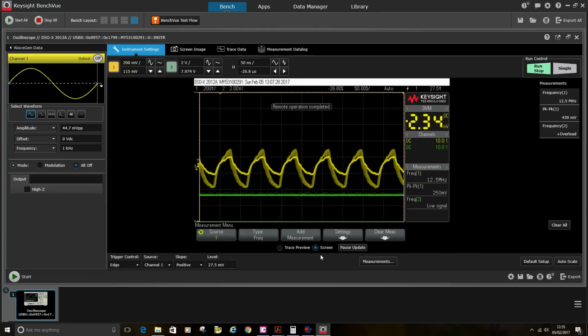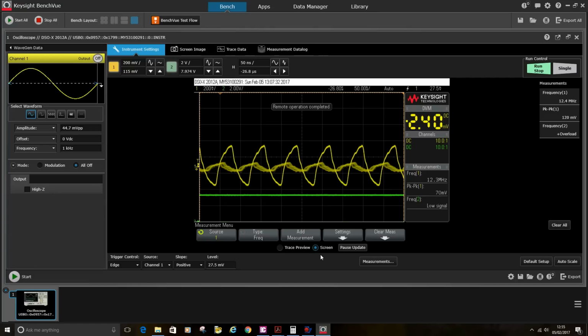Asked the supplier if they could help, but as it is their data sheet on their website, they had the pins all wrong. I mean, for example, there's a reference pin. They said I should go to ground. The reference pin on this sine wave generator is actually the reference oscillator, so sort of 25 megs out, and you ground that. All you're doing is loading up the crystal. So that's what I had on the scope.